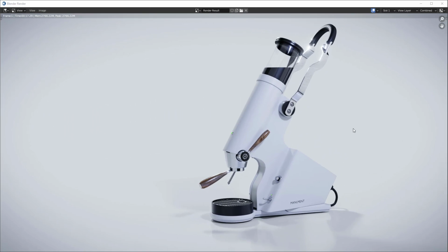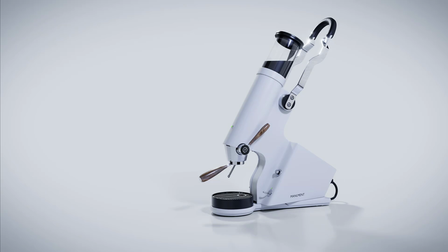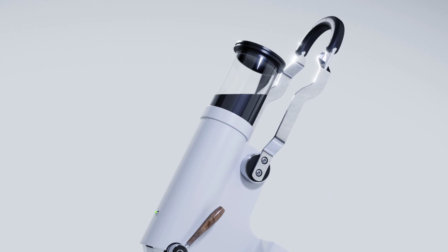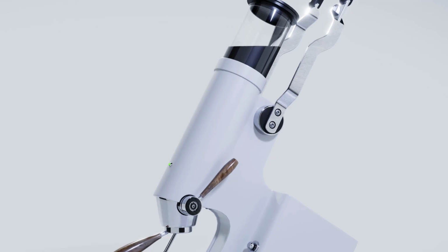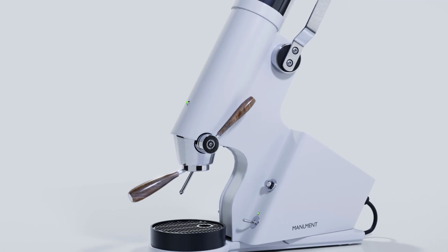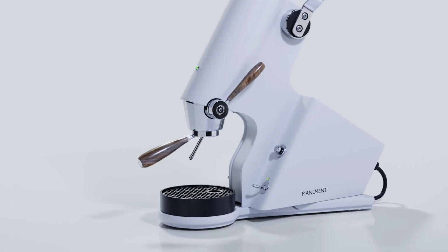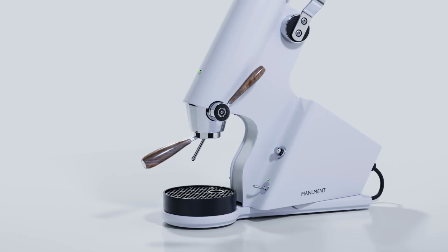So I went back to the original HDRI map because I found out that the one I was using was giving me some artifacting in this glass area up here. And as you can see, the object looks really good. I did adjust the lighting a little more, rotated them a little more. And as you can see, the image is pretty good. And as I said, the 4K was still rendered in under a minute with 256 samples and ultra denoising turned on. It all looks really good.